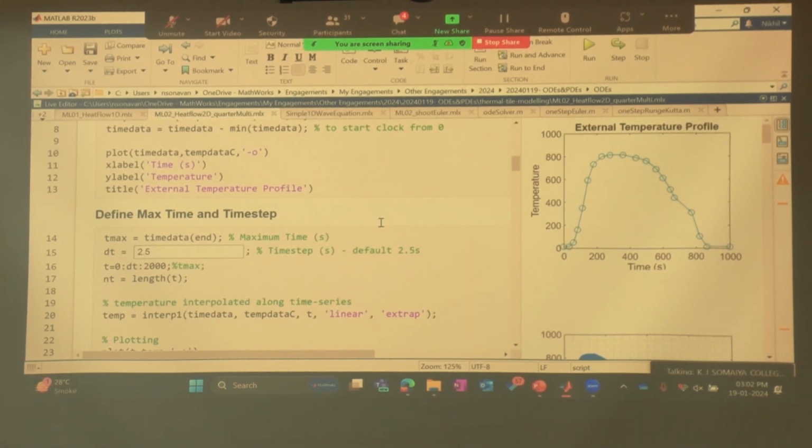So that is why the time step and the solver are the crux of solving any differential equation. Now, if you get a very simple solver, it may do your job, but the same solver may not be able to do the job in other partial differential equations where you need more accuracy. Or if you take the time step too large, the computations are going to decrease, but the result may not be accurate, because every error that gets introduced over here is going to get accumulated. There will be a compounding effect.